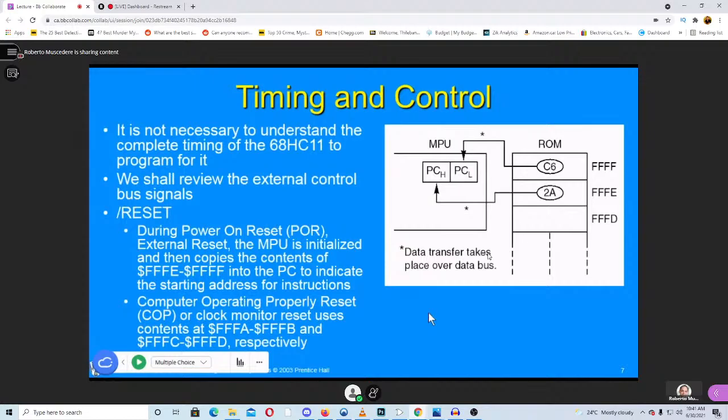Again, these devices could be used in all different places where the environments can be poor. Maybe the power is poor. You might get a dip in power, and that could cause a problem. You may have heard of brownouts before. Blackouts are pretty good things because power is removed completely, and then power comes back and everything is fine. A brownout is actually really bad because power could be removed just enough to cause the system to be unstable but still function. So brownouts are a particular issue.